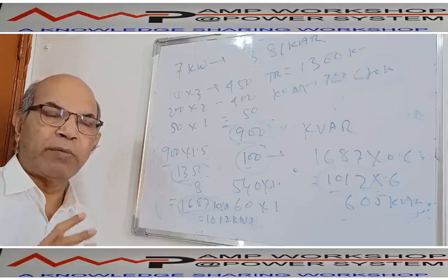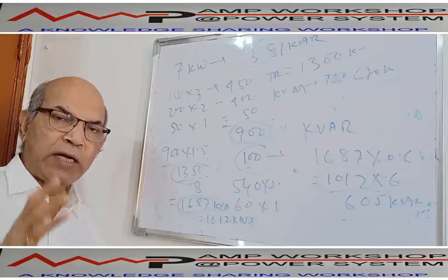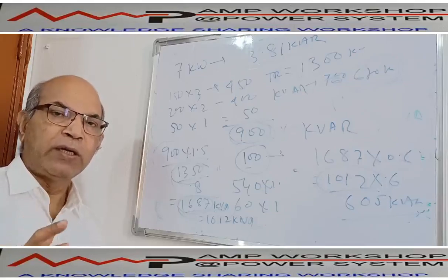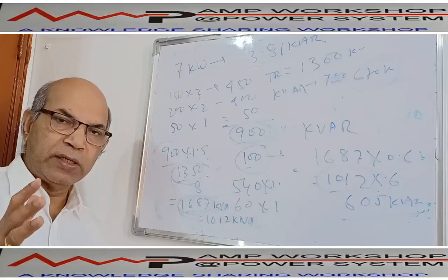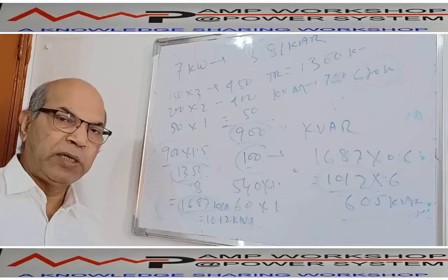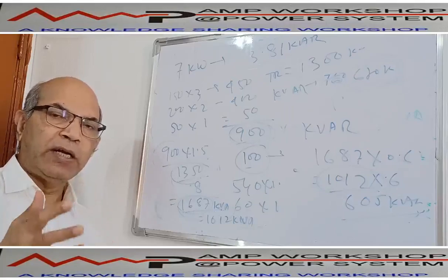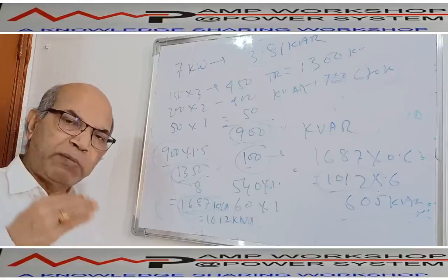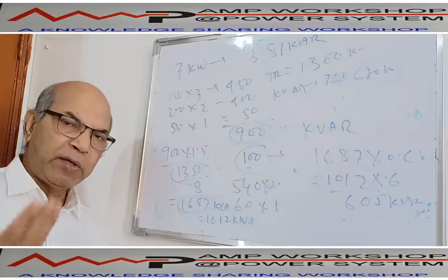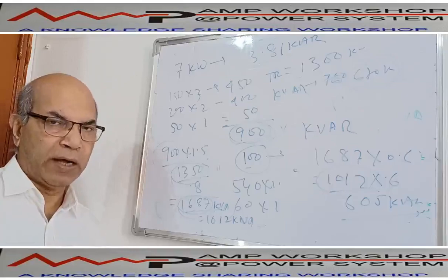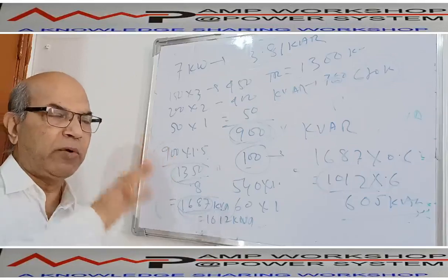Normally for an oil filled transformer, the oil temperature is 100 degrees centigrade total, winding temperature 105 degrees centigrade, and the hot spot temperature of the winding is 115 degrees centigrade. That is, oil: 50 degrees centigrade ambient, 50 degrees centigrade rise; winding: 50 degrees centigrade ambient, 55 degrees centigrade rise; and hot spot we allow another 10 degrees, 65 degrees centigrade rise. So this will be the guideline for the transformer.